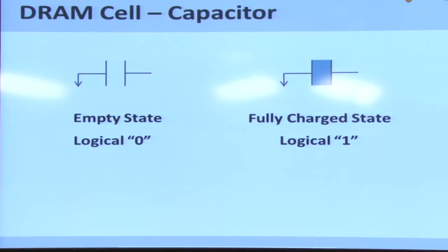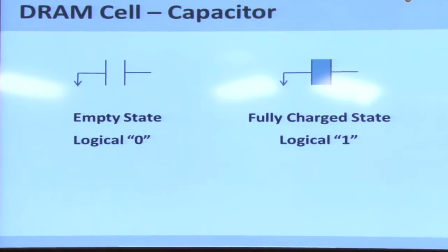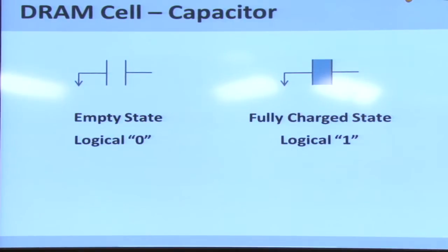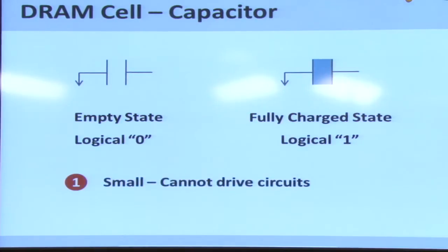So someone mentioned capacity. So if I wanted a high capacity from my DRAM chip, what would I do to these capacitors? Make them smaller, right? So when you make them smaller, what happens? The charge capacity reduces, right? So essentially, my goal is to build really high-density DRAM, and if that is my goal, I would make these capacitors as small as possible. But as I make them smaller, the amount of charge in these capacitors is also low. Right? So essentially, we have these 2 problems.